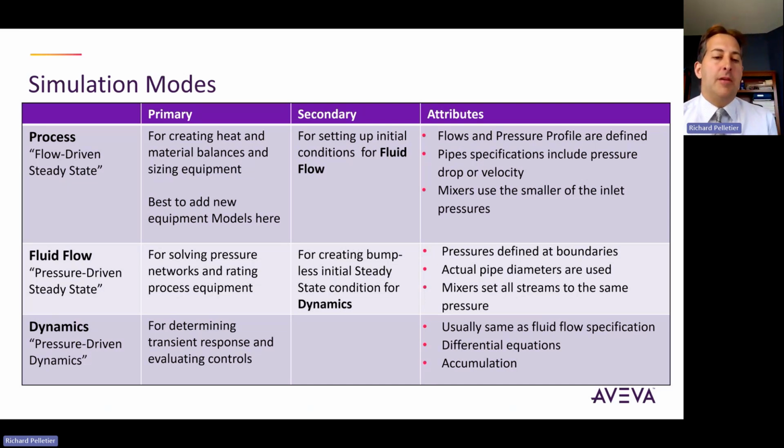Typically, changes in dynamics are going to be set point changes in controllers, or some kind of process condition change like a boundary pressure, or some other type of model condition that you have the ability to adjust. Now, what you will find in dynamics is typically you don't have a whole lot of things that you can change or adjust yourself from an operating conditions perspective, like temperatures, pressures, flow rates.